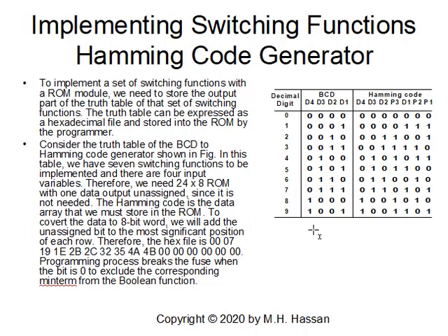After we finish minterm 10, we have to continue to minterm 15, so minterm 10, minterm 11, and so on, by adding zeros. So the last byte that you can see here is all zeros, because we have to put this data, otherwise you will get an error because the data have to be burned completely into the chip. It means those are really not used, and we will have zeros.